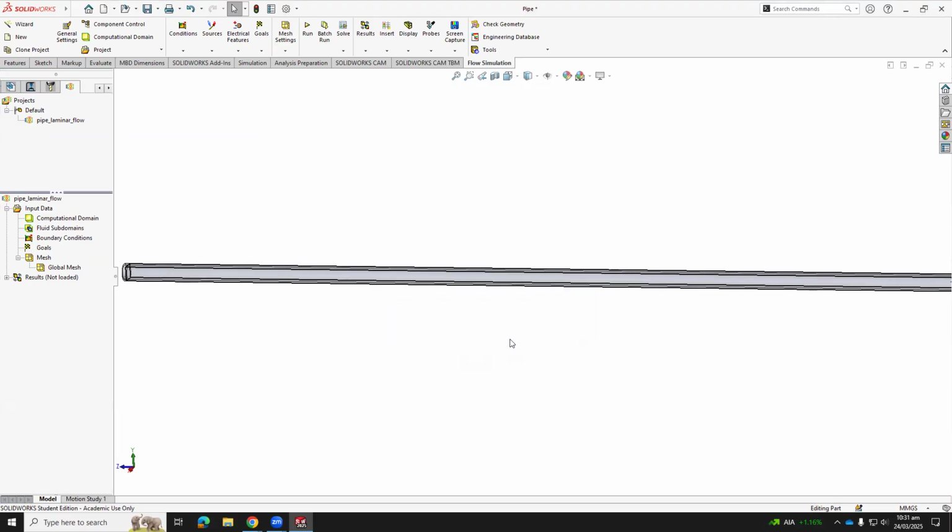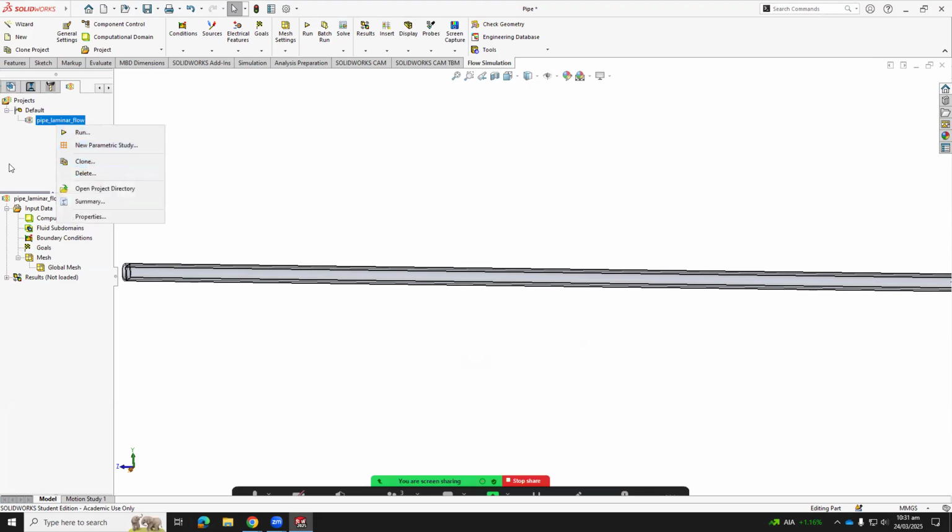Okay, so yeah, now that's what I was mentioning before. It would generate for you. Now we enter a new addition to the software. You can see that is the sample of SolidWorks Simulation. That's where I can understand there is simulation. This is the first study. In the FEA, remember, we used to have the new studies here next to the motion study. Remember, static 1, static 2. In CFD, they are here, on the top. And every time I want to copy, I right-click and use clone. The clone is the copy, meaning I'm copying the study to change things from it.